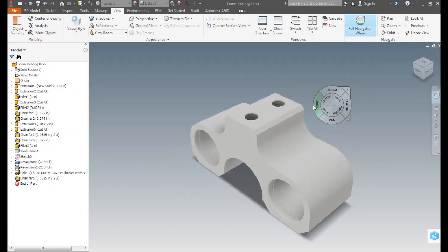To get rid of the steering wheel, press Escape or just click on the icon on top of the navigation bar. This icon will work to invoke it too. The navigation bar is another place where we can activate viewing commands. One just has to select it on the bar, go to a place on the graphic window and hold and drag accordingly. This command will continue active until pressing the Escape key.